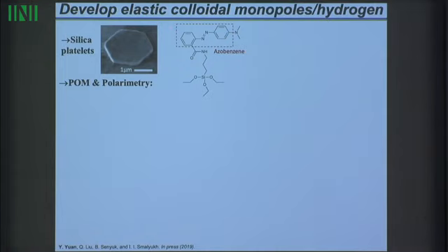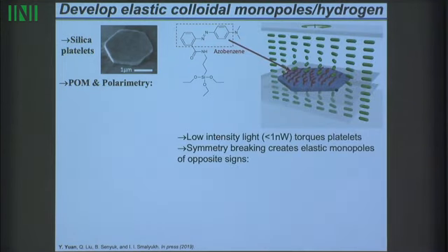They are half a micrometer in thickness and just a couple micrometers in lateral dimension, so even smaller. We can graft azobenzene-unit-containing molecules on the surface of particles, put them in liquid crystal, and then use light to control the alignment on the surface.